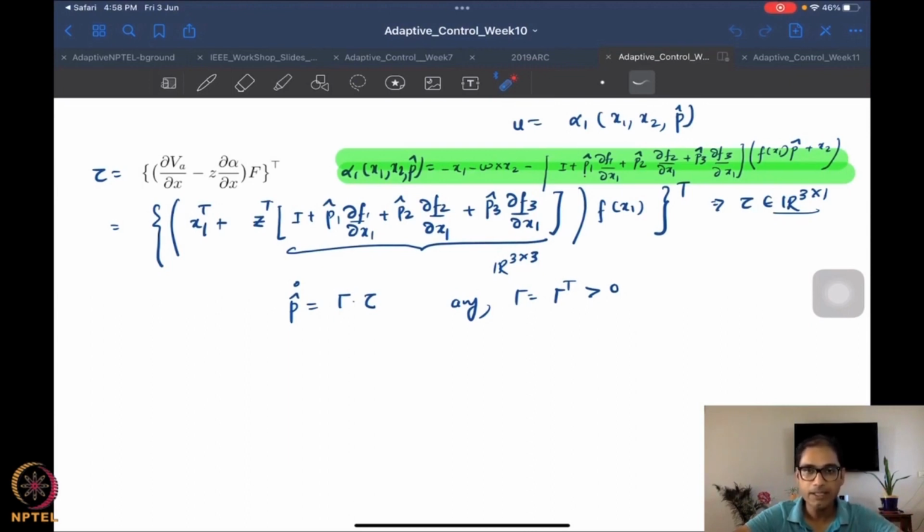In the integrative backstepping method, the issue was that there was an additional estimate for the same parameter. And in the extended matching design, the issue was the appearance of theta hat dot, in the one level extended matching. That is when the control was one level below the unknown parameter. But here, in this case, nothing of that sort happens. You do not see any p hat dots appearing here.